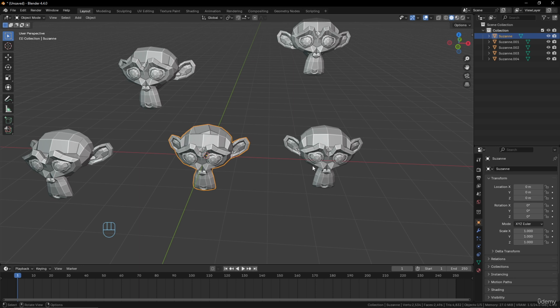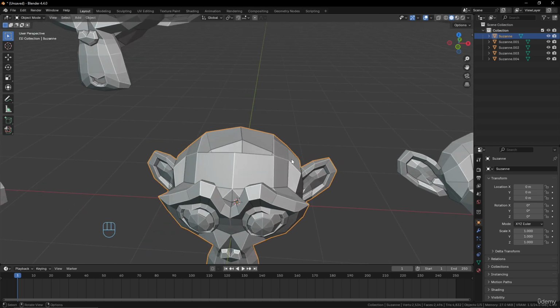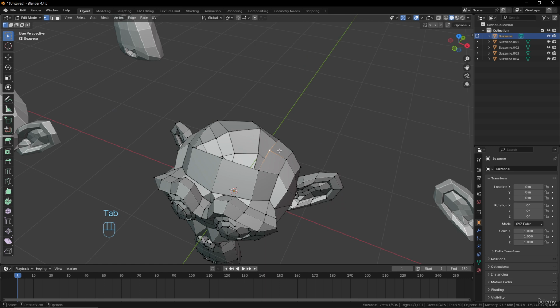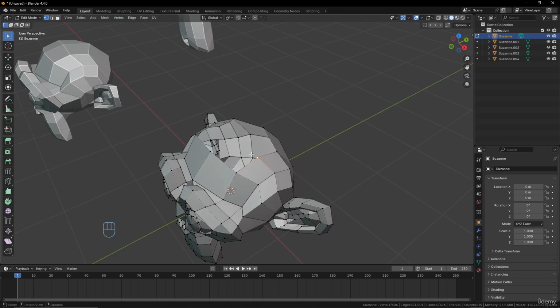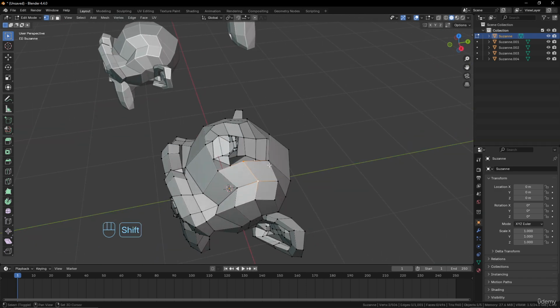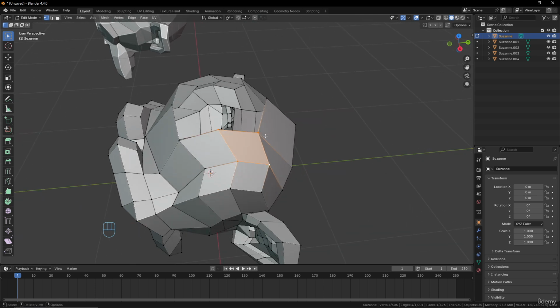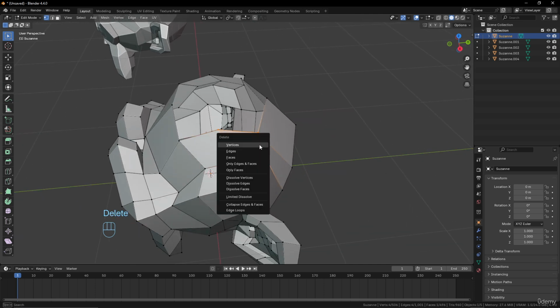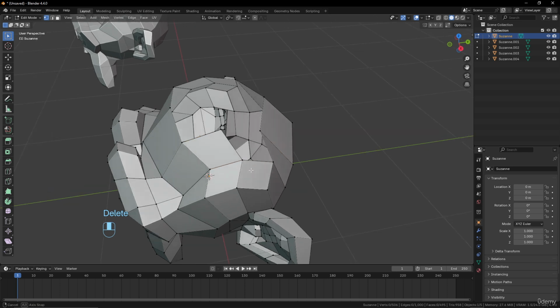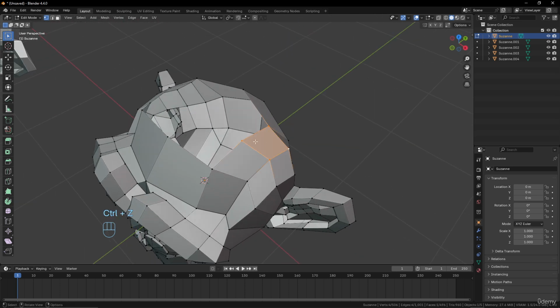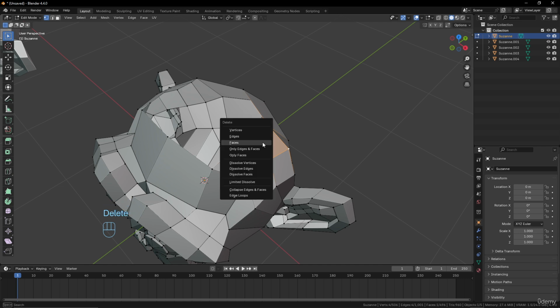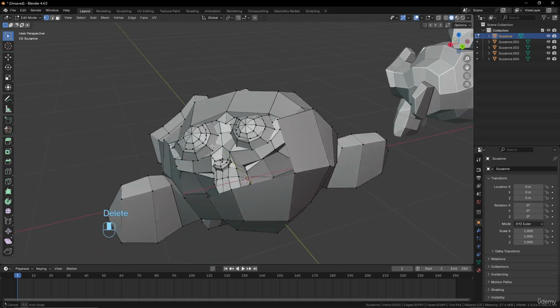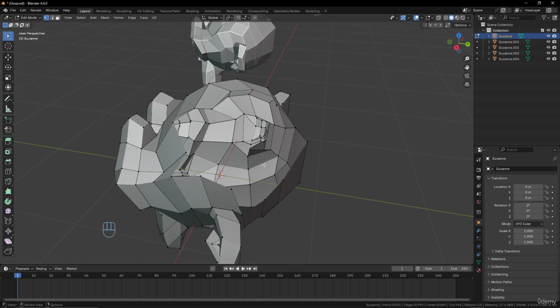The first shortcut that we did see, okay, it's to remove geometry. You can remove with delete, you can remove vertices, edges or faces. So for example, if I select this face, if I have this selection here, I can remove the face, okay? So with X or delete, you can just remove the face. If you delete the vertices, it will delete more geometry because vertices are linked to other data, okay?